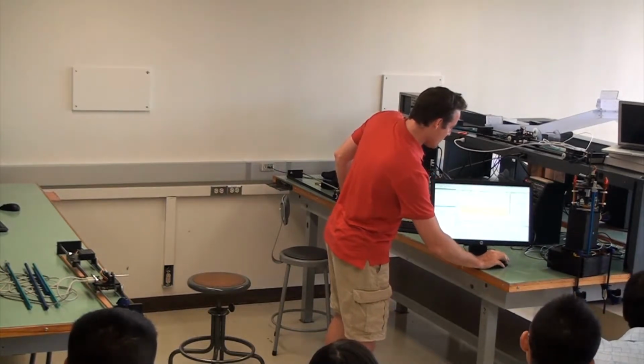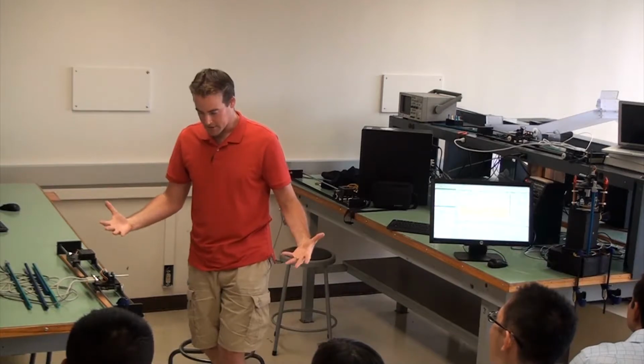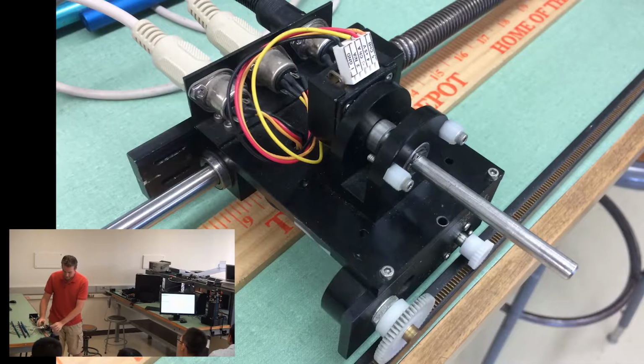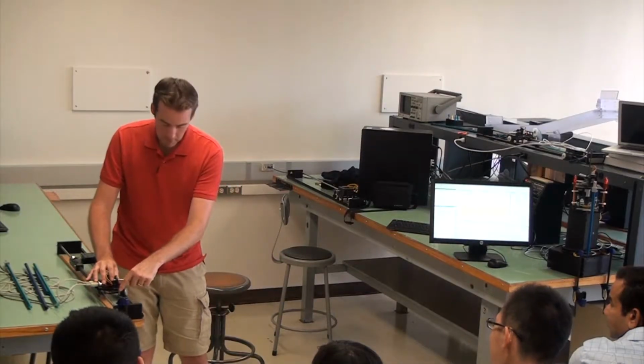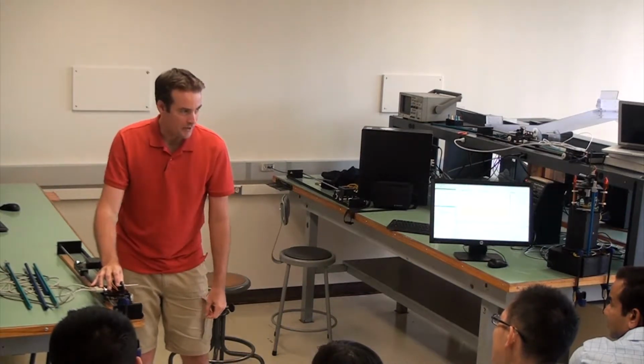So when you take the ECE 147 series, you will get this hardware. You'll get some teammates, you'll get this cart. The cart has a little motor on the bottom that has this little gear. This is a gear also, so it can move back and forth like this. There's also a little encoder here, a rotary encoder that can measure the angle of this gear. This gear is not actually driven at all. There's no motor attached to it. All it does is read out the angle of the gear. And you can figure out using the sensor, therefore, the position of the cart along the track.